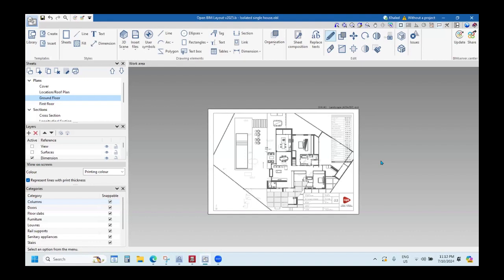But here, once you are working with CYPE, it doesn't matter, as you have the capability to import the IFC file format into our software. Assume that you have Revit, ArchiCAD, Allplan, or a model from any other architectural tool. You can ask them to generate the IFC file format, and then you can import it into CYPE architecture. And once you have it here, you can integrate it with CYPECAD.